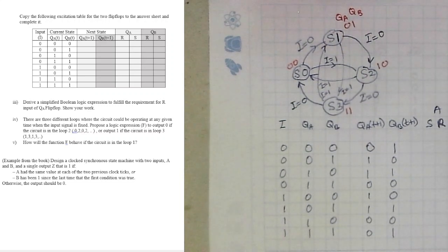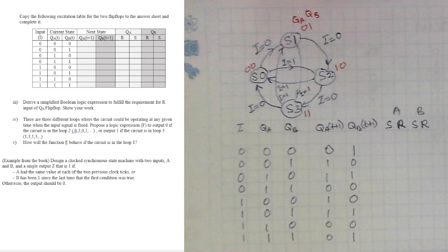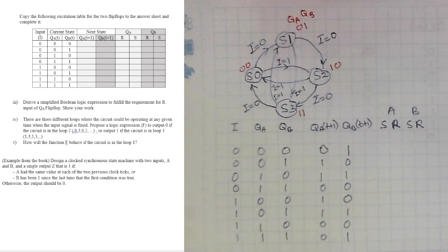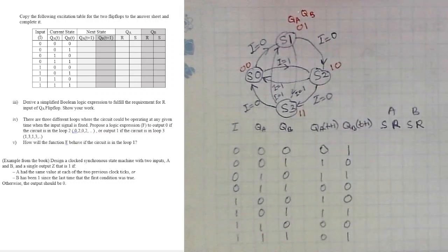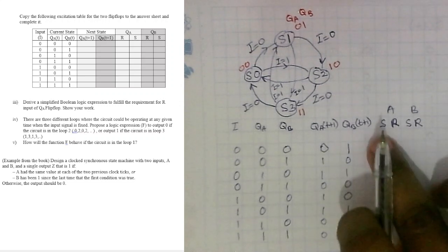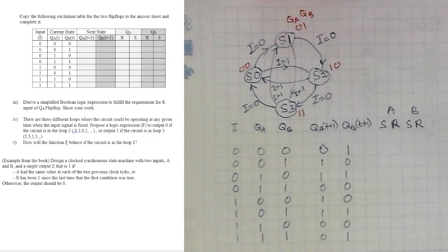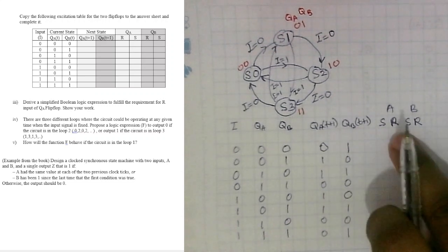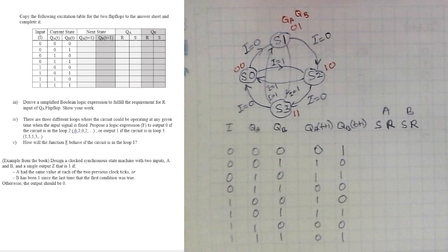Okay, it's just cranking the lever, nothing much to think about, so you have to just follow the procedure. So now we know all the transitions. This entire thing is represented in this table now. But we need to determine all the excitation signals, and we will be deriving the Boolean expressions for each of these signals so that we can implement a circuit accordingly.